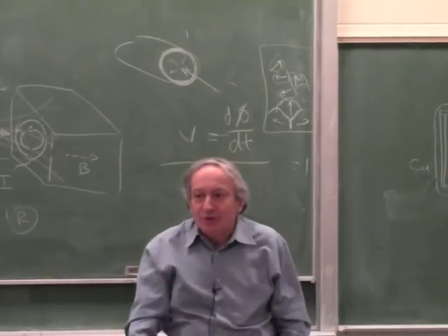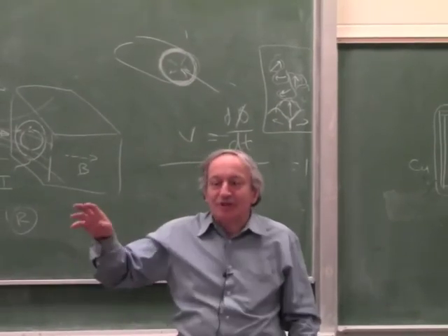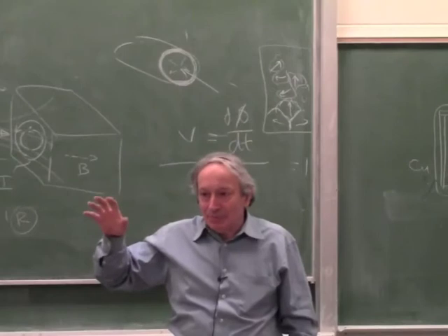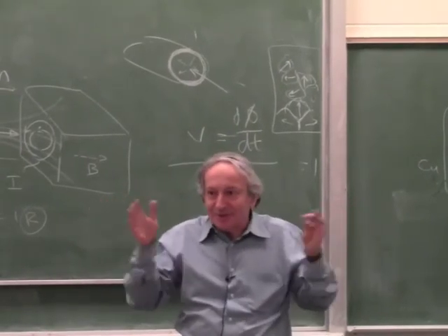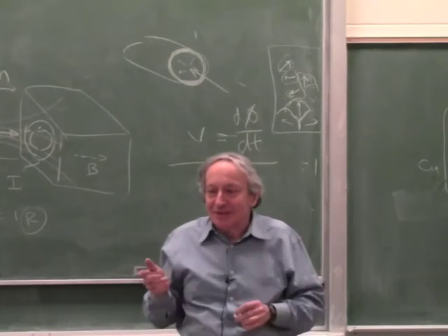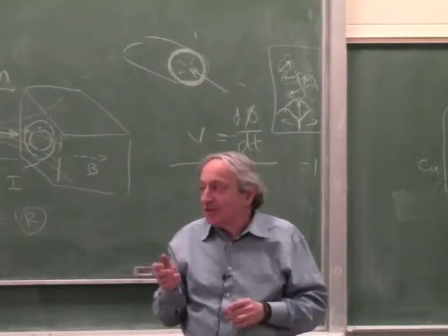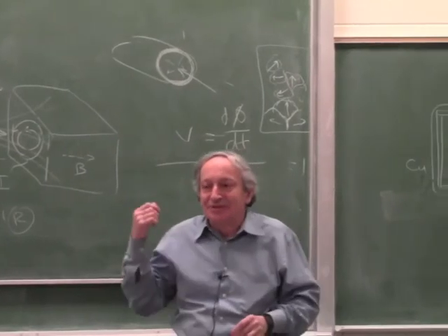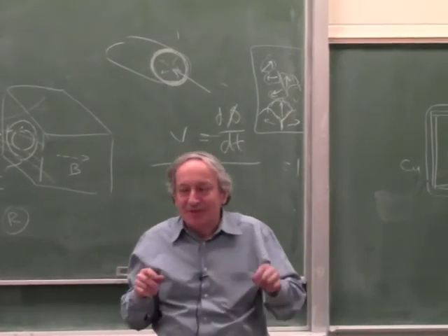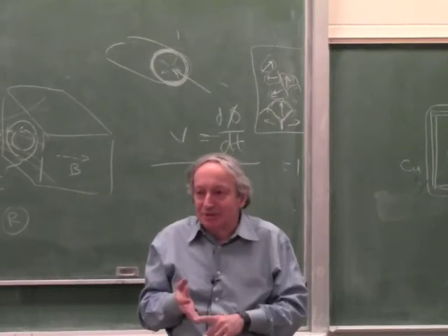You know, when you walk near a power transformer, you can hear it humming. Right? This is magnetostriction. The whole transformer is growing and shrinking 120 times a second. So there is actually mechanical movement too, but anyway, all this is getting too detailed for the time we have. So read up on magnetic domains and magnetostriction.